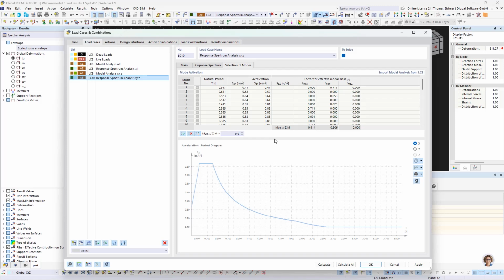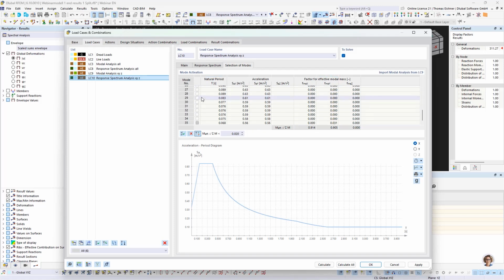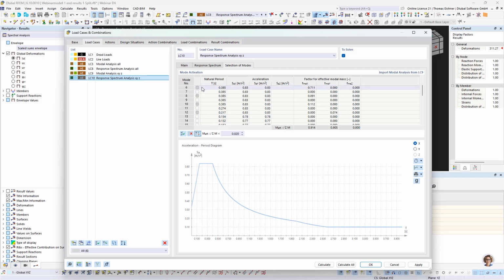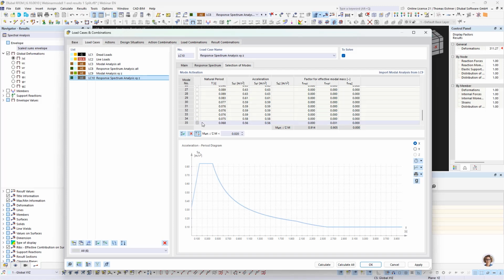We will neglect all the ones which are, let's say, that's some testing, all below 2%, and we will still be over 90% in the y direction, so that's possible. And with that, we will lose again about 2/3 of our eigenforms. What do we have left? 1, 2, 3, 4, 5, 6, 7 modes.